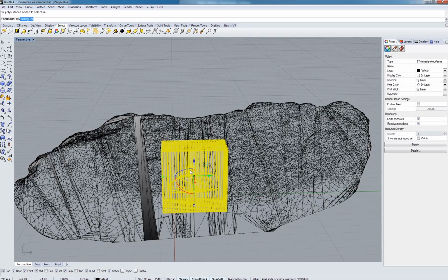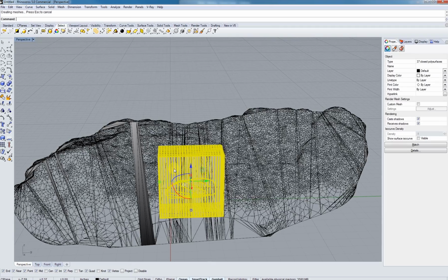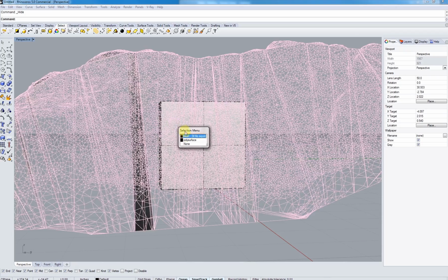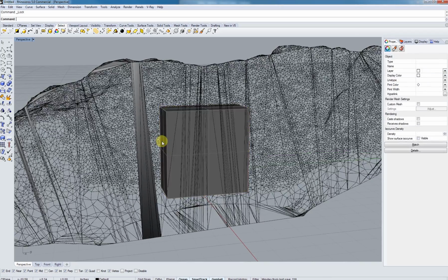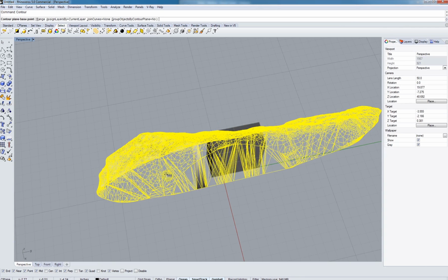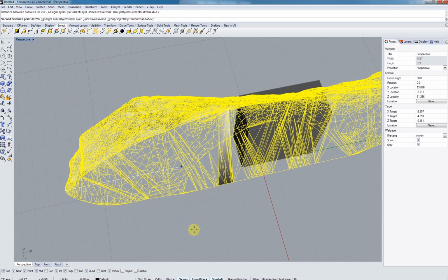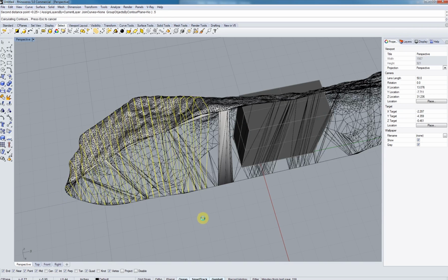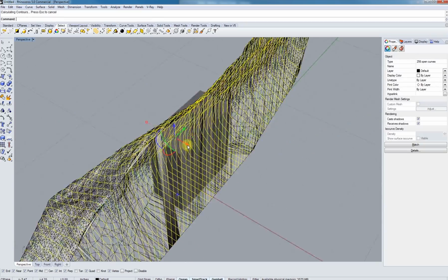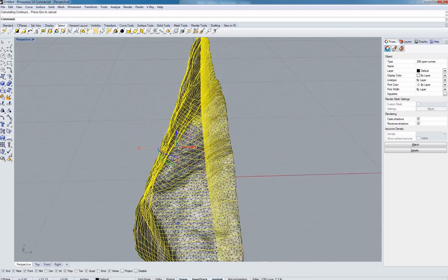Perfect. So after this, what I'm going to do is just take my pre-existing box that I had from the last assignment and hide my waffles away, so we just have a lock box in there. I'm just going to lock that using Control L. So next we're just going to do the same operations for the past assignment with contours. This one I'm just going to slice it up at 0.5 inches all the way across. This should go relatively quick.